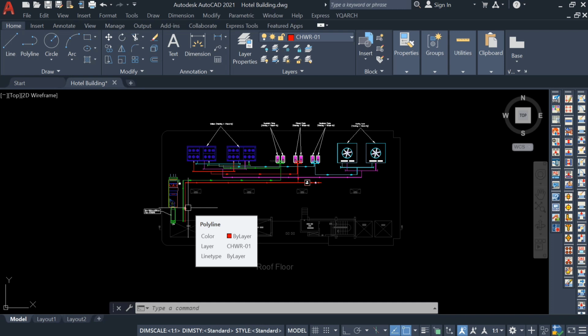However, as a general guideline, 1 ton of refrigeration typically requires a flow rate of 2.5 GPM of water in a standard chill water system. So remember, in a closed loop system 1 TR is equal to 2.5 GPM.